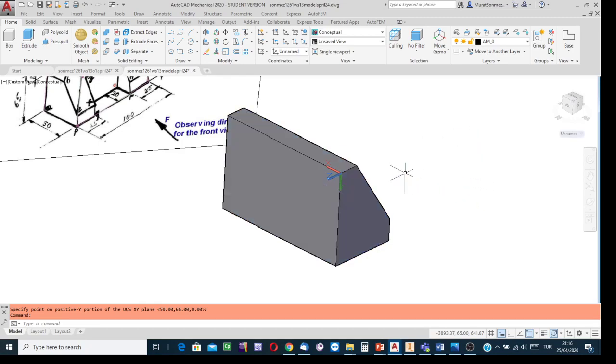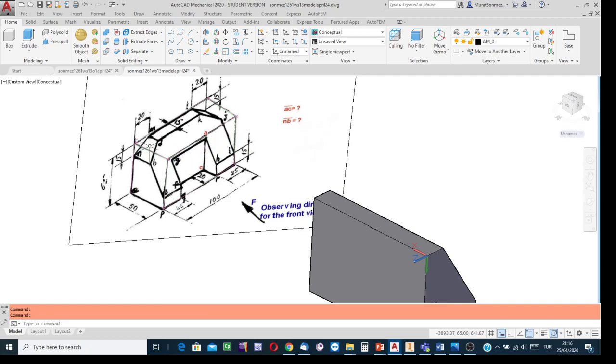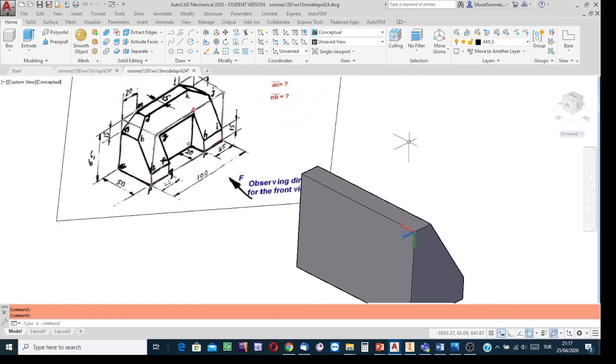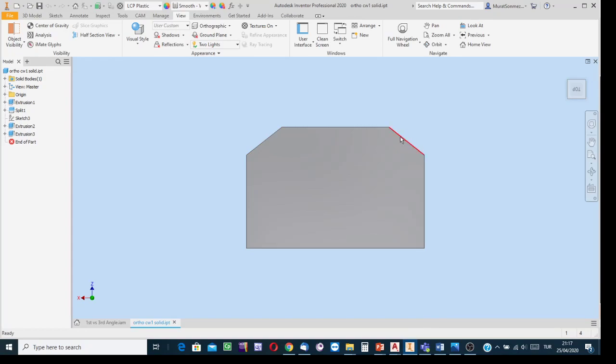So I can start drawing the edge of the trapezoidal surface. The lower boundary is 15 millimeters away from the top side surface. The upper boundary relative to the profile side is 20 millimeters away. So 15 and 20 are the coordinate values for the inclined line, say here, which corresponds to the edge of the trapezoidal surface. Origin is over here. Relative to the origin, 20 is the coordinate of this, 15 is the coordinate of the other.